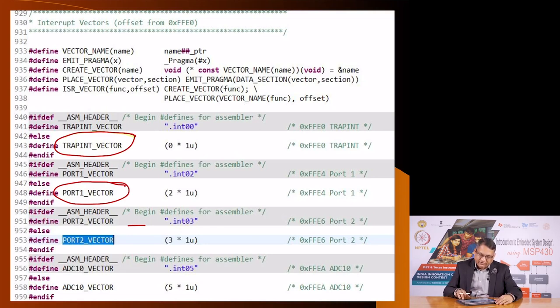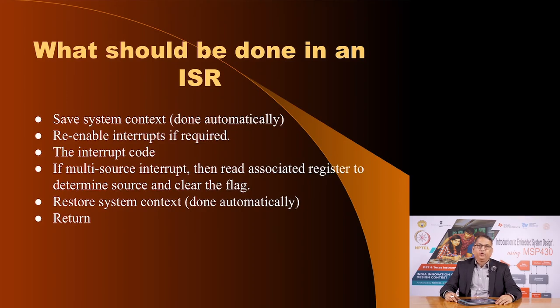We will illustrate it with an example. Now, what do you do? What happens in an interrupt subroutine? Well, the moment the main program is interrupted, you must save the context. And what do I mean by the context? Context is reflected by two things, the status register plus the program counter. So, both these registers have to be saved, so that you can resume using the values whatever program was interrupted. This is done automatically by the microcontroller. How? It saves these two registers on the stack.